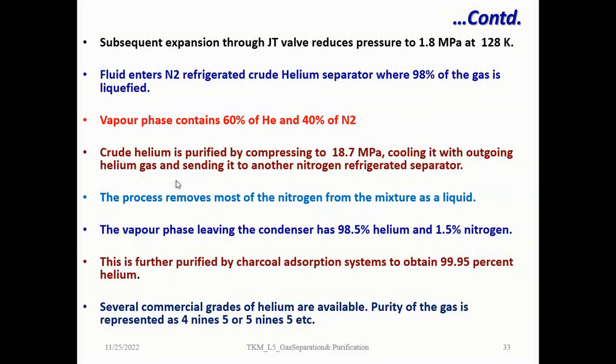This crude helium gas is compressed, purified by compressing to 187 bar and cooling it with outgoing helium gas, and sending it to another nitrogen refrigerated separator.